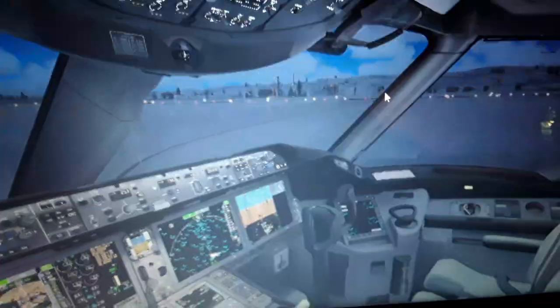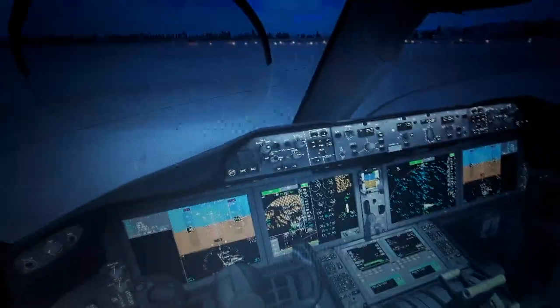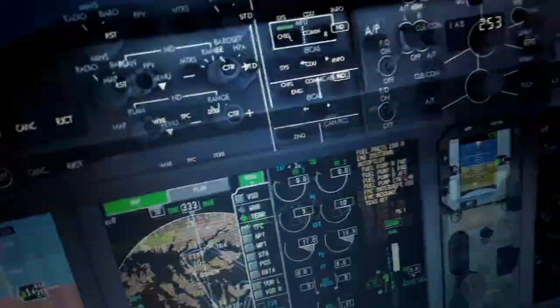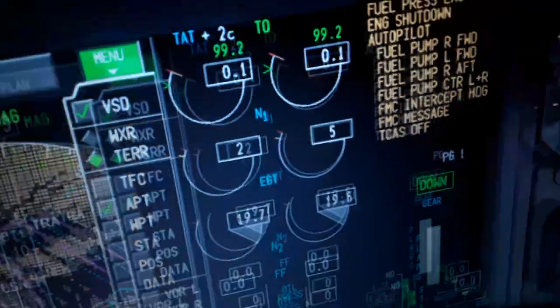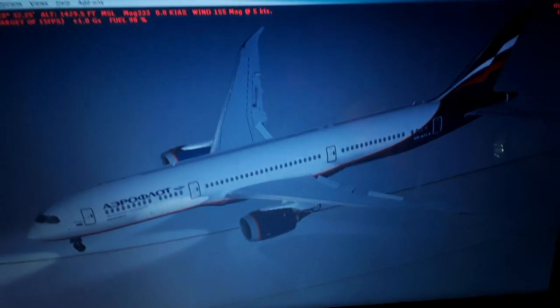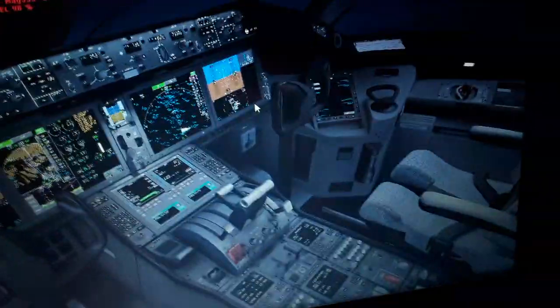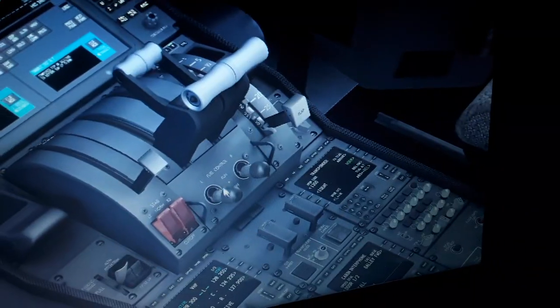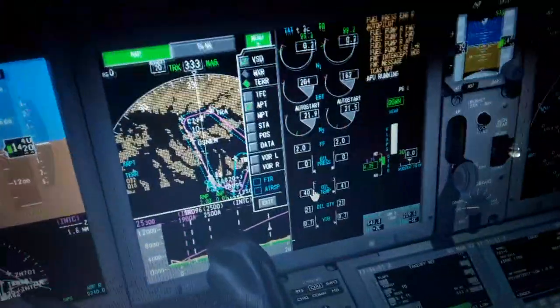Now we have bleed air from the APU into the engines to start them up, to pressurize the engine starters. So above 20% we can initiate the fuel flow. We can see we have only the pressurizer right now. So we initiate here the fuel control, both left and right fuel valve. It will take like 1 minute and we'll go for takeoff.